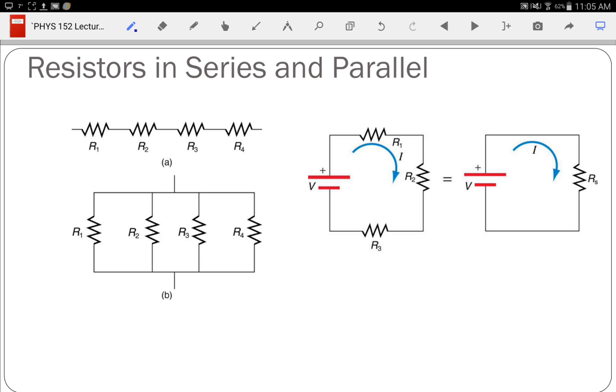So this stuff. In the lab, we saw resistors in series and parallel. Which one of those is series? Okay, the top one. I asked that question just to make sure we're on the same page, there's no confusion. In series, what has to be the same for the elements? The current is the same for all of them. The lower one is in parallel. What's the same for all of those? The voltage. And then we have over here the idea of the equivalence.